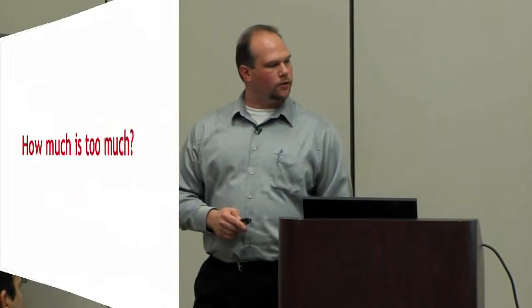You can also have equipment malfunction. For the VFDs, we create harmonics. We really don't care. We'll create all the harmonics all day. But you could have problems with your zero crossing, or if there's too much voltage distortion, you could cause flat topping with that small transformer where we saw the top of the waveform chopped off because of harmonics. You can also get a resonance in your power system if you've got power factor correction caps. You can make them start to oscillate and cause overvoltages, spikes. Other things can occur in your system.